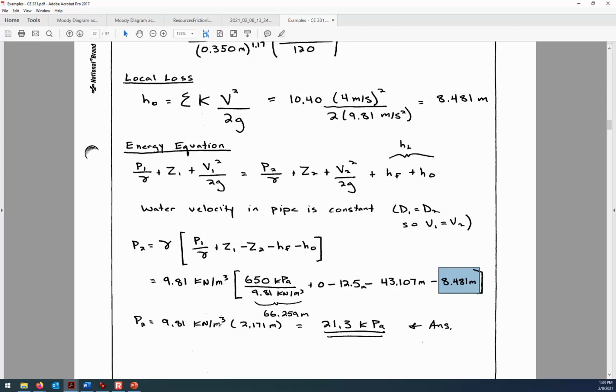And I think earlier in the semester I may have mentioned that we have a lower limit in typical times in a water distribution network. You really wouldn't want the pressure to go below 240 kilopascals, and maybe in an emergency situation like a fire where they're just drawing a lot of water out of a hydrant, it would be okay for the pressure to temporarily get down to maybe 140 kilopascals.